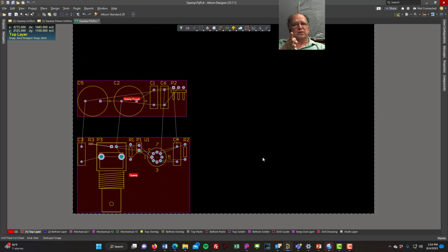I can look at that channel and say, look, there's a master gain. There's 3 tone controls, right? High, medium, low. There's a pan control, left and right and all that. So that's one channel. I can draw that channel in Altium and then tell Altium, repeat this 16 times because I want to have 16 channels, and it'll put all those parts into 16 rooms.